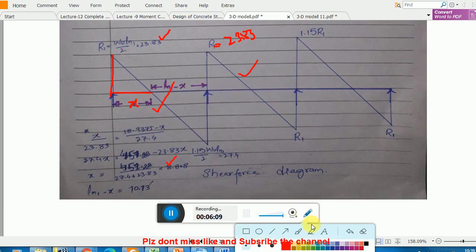So you see the total loading will be how much? Remember, the total reaction which is provided by the column to these two beams, basically from both sides, is 23 plus 27. Okay, so this is only from two sides. Now we have to account for four sides. So that's why we add these two, 27.4 plus 23.33, and multiply it by 2 to account for four sides.